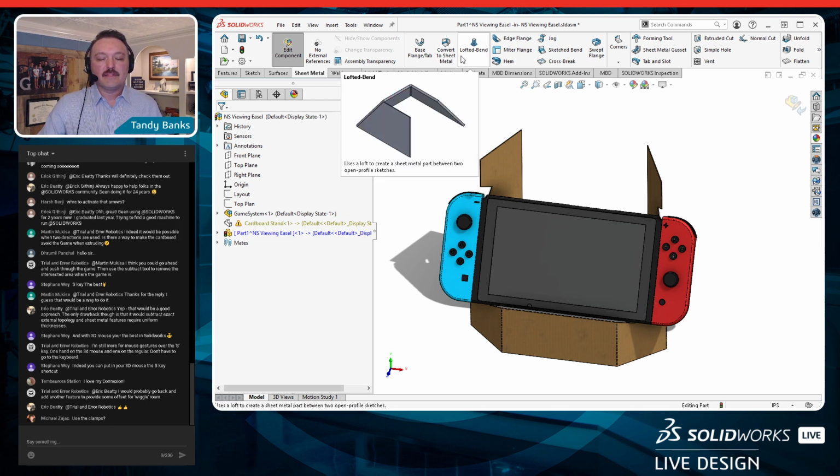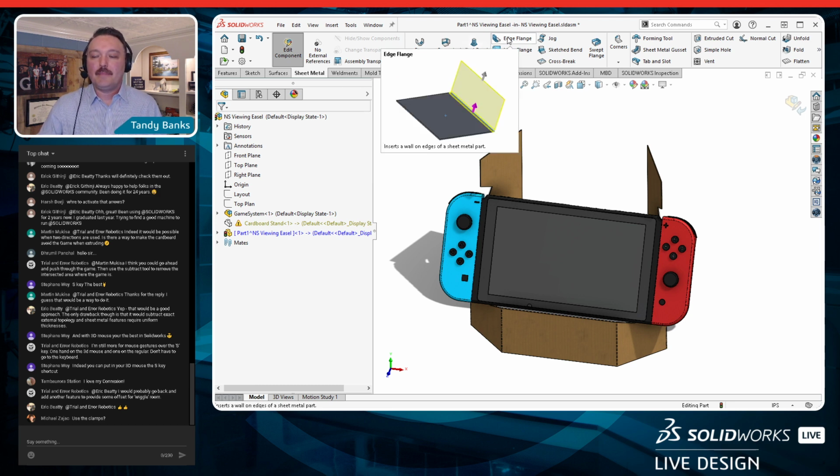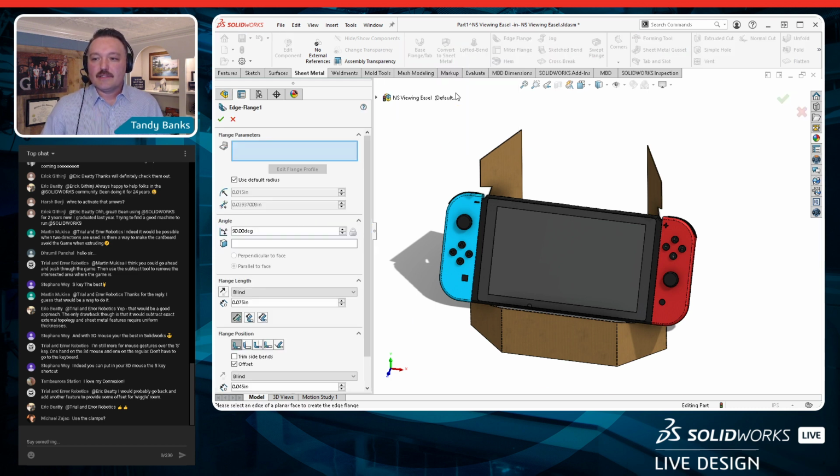I've used lofted bins a lot for different geometries. These are great for transitions and hoppers and especially HVAC stuff whenever you're going from rectangles to circles and all those kinds of things. And so lofted bin, great tool. But I'm going to camp out over here in edge flange. This is my buddy. I use this tool so much.